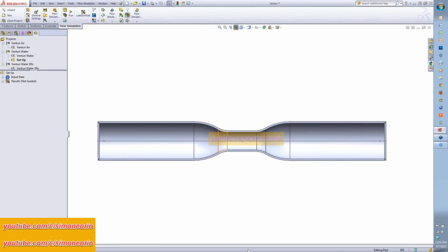So let's go ahead and jump into SOLIDWORKS. Everyone here is familiar with the SOLIDWORKS interface. We have the command manager up at the top, and when you add in the Flow Simulation add-in, you get a new command manager. And we have this Venturi set up. There's a lid on either end, basically capping this volume. And we want to start off by telling the software what our inputs and boundary conditions are. And Flow makes this really nice because it gives us a wizard to do this.